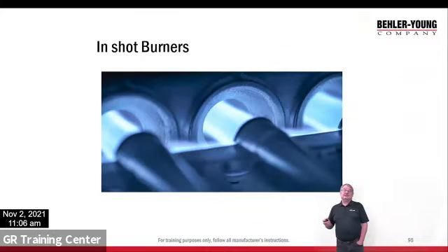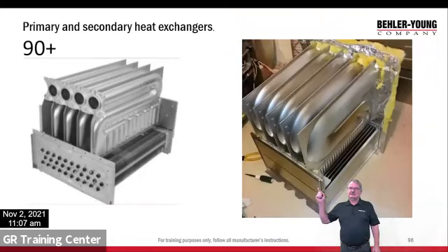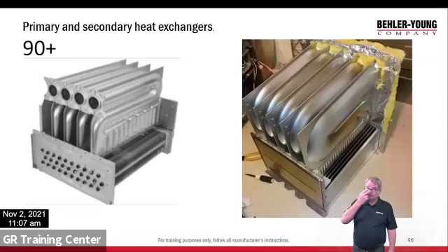So now what I did is we're going to invert our setup here. And the burners are going to go at the top because we're doing draft induced. Now we're forcing the flue gases, so we don't have to worry about gravity anymore. We're forcing the flue gases through there, so they're going to go down through that heat exchanger. And instead of going outside, they're going to go through this secondary heat exchanger. So now we might have 250-degree gas going into this bottom heat exchanger, or secondary.